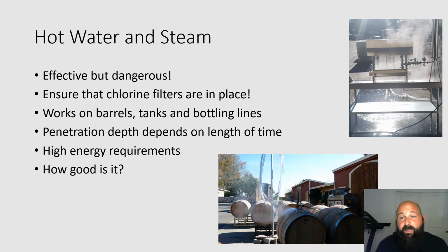The thing is, you've got to make sure you've got plenty of power. If you're some small home winemaker, steam is pretty hard to generate on a home service. But in commercial settings, you're going to want to make sure that you have around 60 amps of power at 220 at least, if not more, or 240, to be able to power a steamer. Having some 480 volt service is also really nice to be able to power a steamer properly. You're going to need a lot of energy. You can also get steam from diesel if you have one of those, or gas if you have one of those pressure washers that's designed for it. But just realize you're using a lot of energy. That's the downside to it.